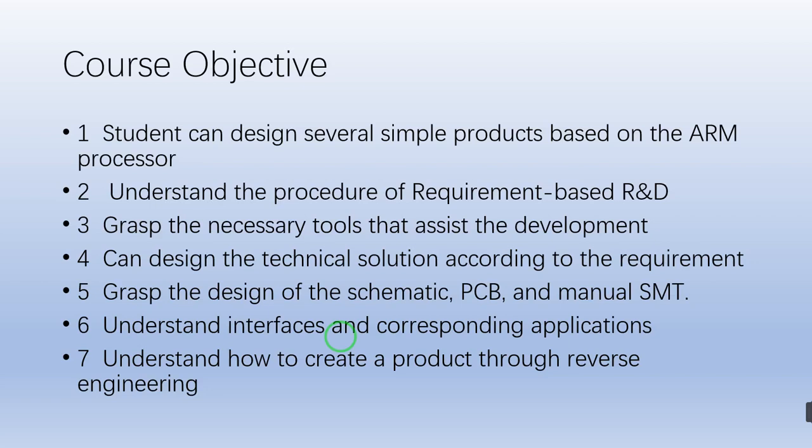So using the serial port, the processor connects first with the module, and then the module connects to the tower, then to the cloud. So this is interface. Different products need different interfaces. The most commonly used interfaces are I2C, SPI, and serial port. These are very common interfaces.